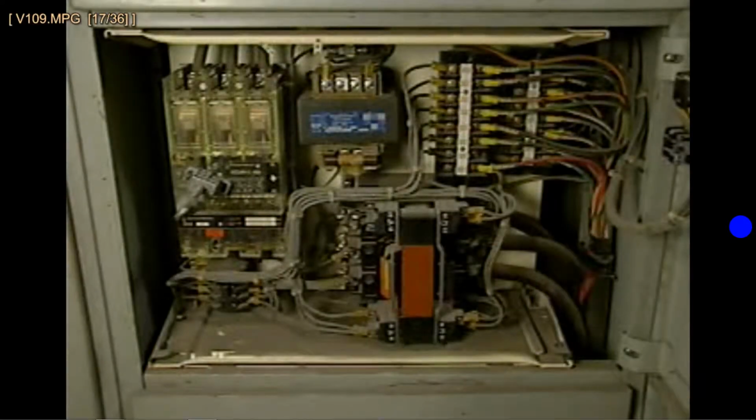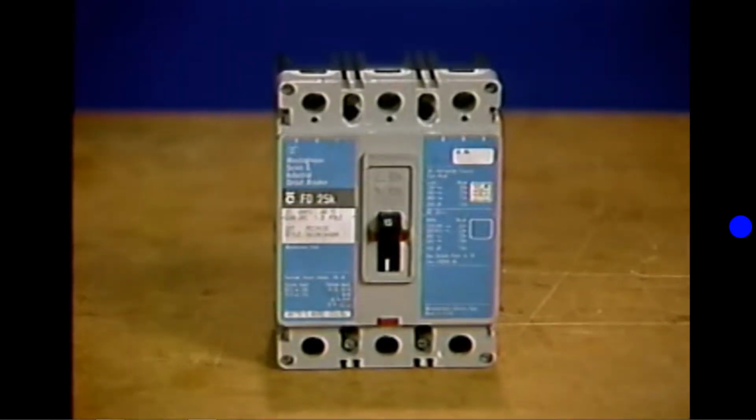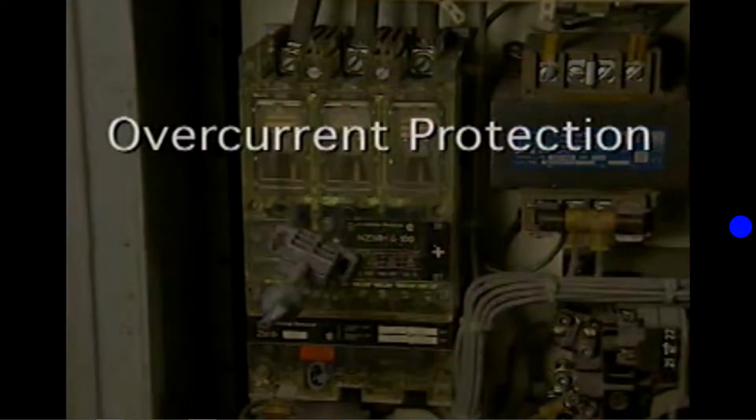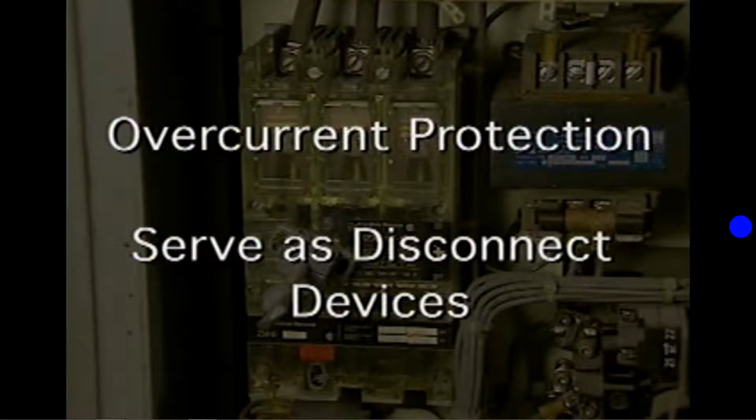In this part, we'll look in some detail at typical molded case circuit breakers that are used in motor branch circuits. A circuit breaker is a device that is used to interrupt current flow in a circuit under normal or abnormal circumstances. A molded case circuit breaker is a circuit breaker that is fully enclosed in an insulated housing. In motor branch circuits, circuit breakers typically perform two functions. They interrupt the circuit to protect it from damaging effects of overcurrent, and they serve as disconnect devices.